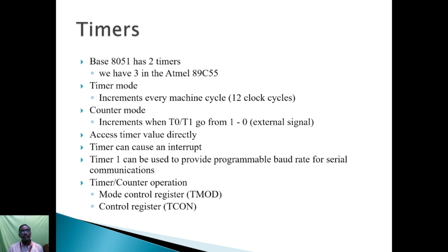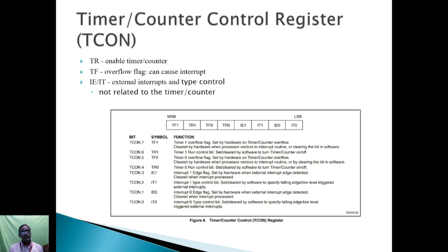Timer 1 can provide a programmable baud rate for serial communication. For timer counter operation, there is the mode control register, TMOD, and the other one is the control register, TCON.